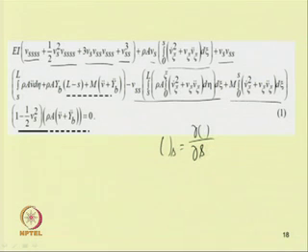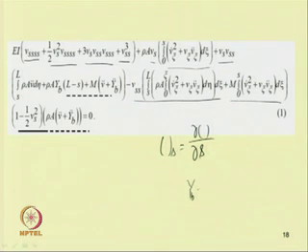But one may note this term, where one can find this coefficient of v_s squared equal to v double dot plus y_b double dot. This y_b is the base acceleration of the base motion. So, if one represents this y_b by Z cos ωt, that means if the base is moving periodically, then this periodic motion is a coefficient of the displacement.